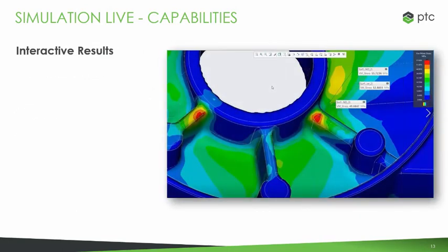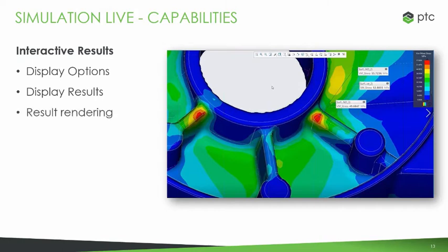And looking at the results that we're getting, they're very interactive. Once we're in the analysis, we have display options available to us that we can alter for whatever our use case happens to be. Depending on the mode of analysis, we have different options for visualizing our results. So for example, in a structural study, we can display deformation, von Mises stresses, principal stresses, and other values around that. The model visualization itself can also be altered to view different surfaces, different ISO surfaces with color gradients, and also minimum and maximum values. And then to really understand the results, we can animate the model to very clearly display that visualization.